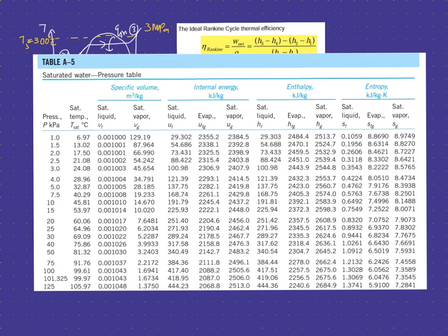Alright, so your state 4 is given the pressure, right? When it gives you the pressure and another property, in this case you assume that your state is in a mixture region. So let's take out your ruler and place it on 50 kilopascal.